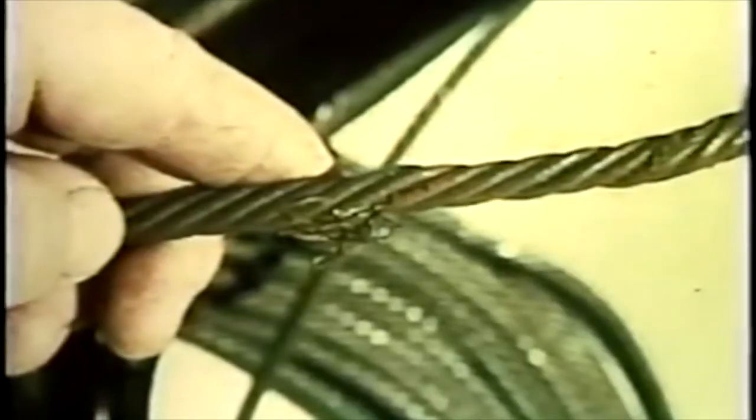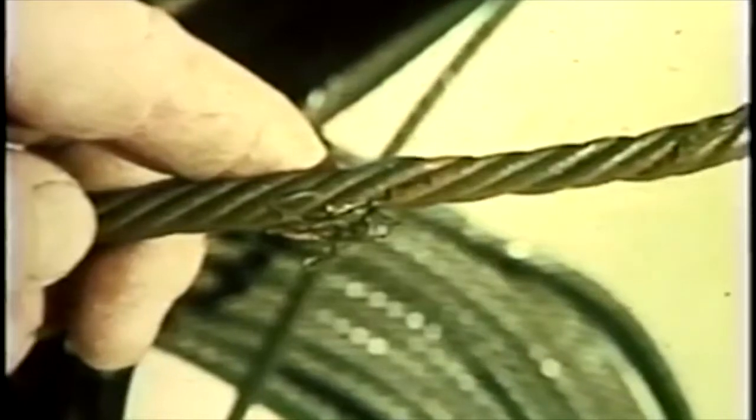Make sure anchors are secure between scaffold and structure where required. Verify that all guardrails are in place and secured. Inspect motors on all power-driven scaffolds for proper operation and certification. Check ropes on all suspension scaffolds for proper size and for signs of wear or deterioration.